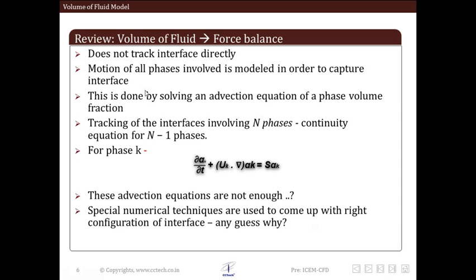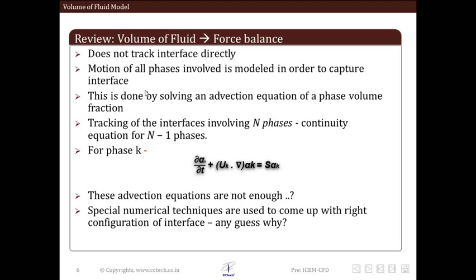Now we will have a quick review of what the volume of fluid model does in order to capture the force balance. Now the VOF model does not track interface directly. Motion of all phases is modeled in order to capture the interface. That is, a separate governing equation is not solved for just tracking the interface. What it does is solves the motion of the phases involved and indirectly captures the interface. Now this is done by solving advection equation of phase volume fraction.